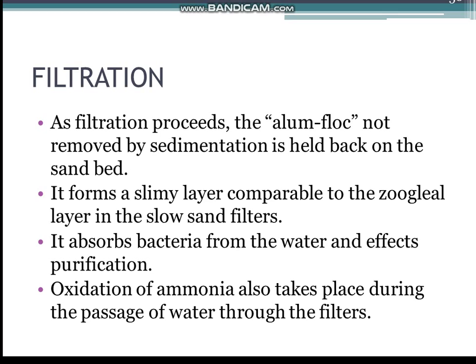Filtration. As filtration proceeds, the alum floc not removed by sedimentation is held back on the sand bed. It forms a slimy layer comparable to the Zoogleal layer. In the slow sand filters, it absorbs bacteria from the water and effects purification. As filtration proceeds, the suspended impurities and bacteria clog the filters. The filters soon become dirty and begin to lose their efficiency. When the loss of head approaches 7 to 8 feet, filtration is stopped and the filters are subjected to a washing process known as backwashing.